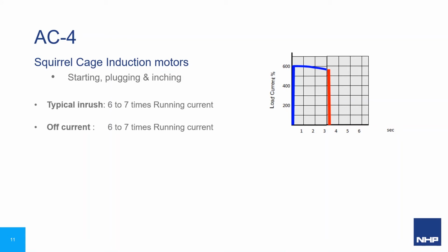Plugging is a method of bringing a motor that is stopped but still rotating with a high inertial load, like flywheels and fans, to a stationary position quicker. Once the motor contactor is opened, the plugging contactor is energized with reversed phase rotation, which attempts to reverse the direction of the motor until the motor is close to zero speed. This application causes severe electrical stress on equipment and mechanical stress on the connected load.